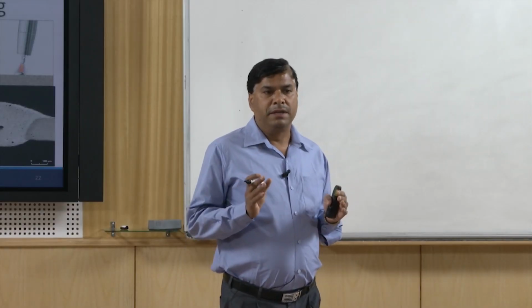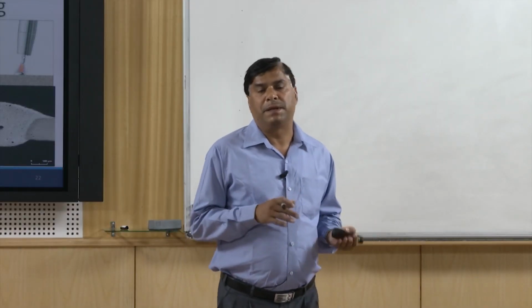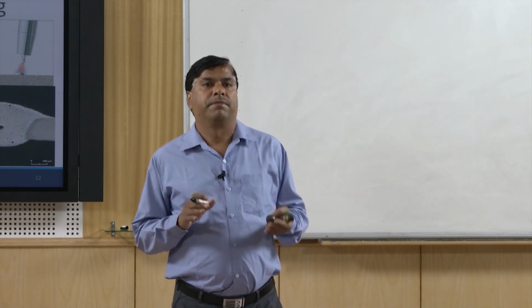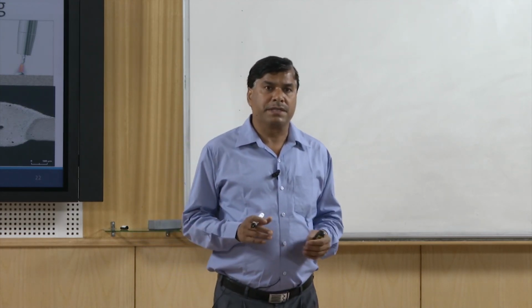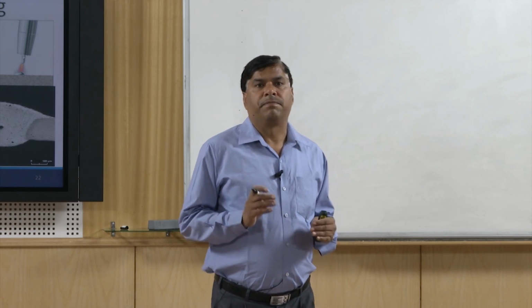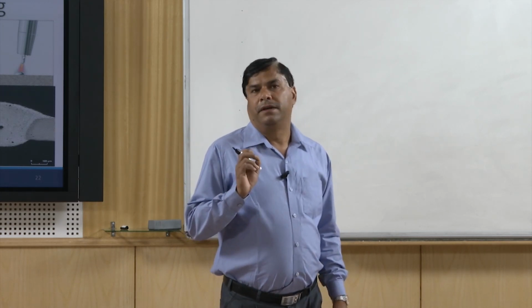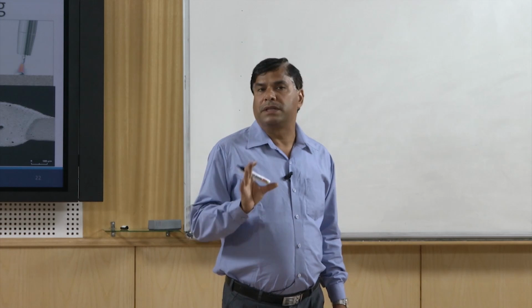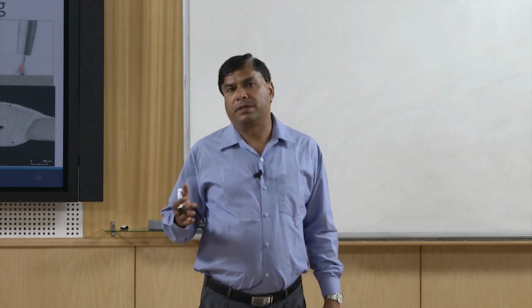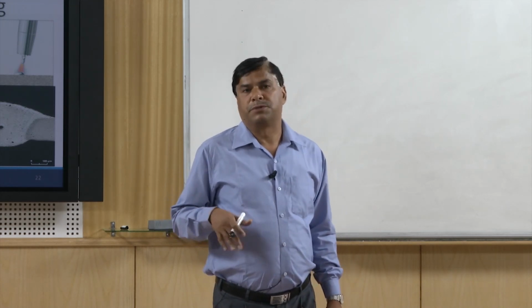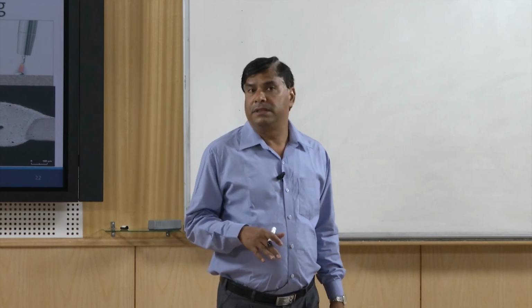In this presentation I have talked about how CMT exploits the positives of the pulse GMAW and the conventional GMAW process, and how it offers good control over the heat input and good control over the metal transfer, so that it becomes useful for joining of thin sheets.